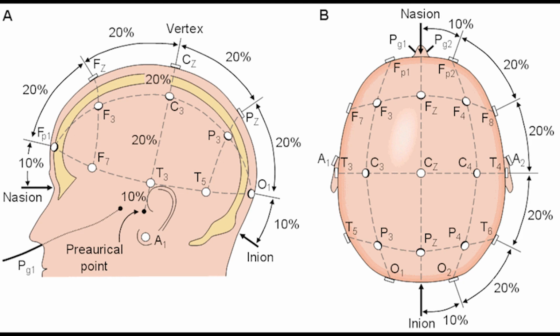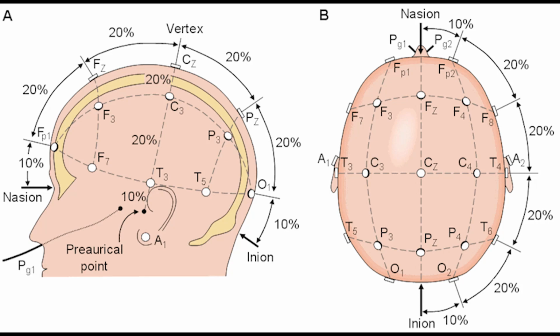To detect these waves, electrodes were placed on the O2 and FP1 areas, and the FP2 area also had an electrode placed to detect EMG, which were those facial movement patterns. Since the O2 area contained hair blocking the skin, as opposed to the other areas, the signal kept flatlining and produced more noise, so to help with that, a headband was used to create pressure for the electrodes to make good contact with the scalp. There is also a ground electrode connected at A1 behind my ear to reduce electrical interference from the body.